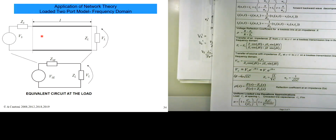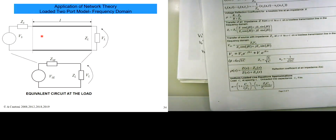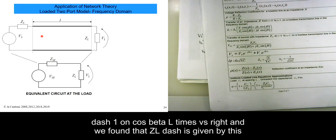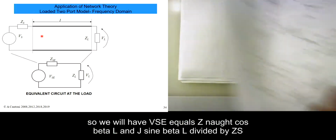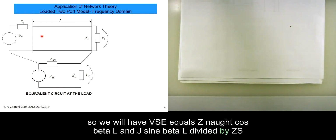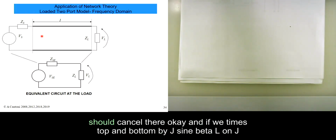We've got VS ZL dash on ZS plus ZL dash equals VSE cos beta L. So VSE equals ZL dash on ZS plus ZL dash, 1 on cos beta L, times VS. And we found that ZL dash is given by this, so we will have VSE equals Z naught cos beta L on J sine beta L divided by ZS plus Z naught cos beta L on J sine beta L, times 1 on cos beta L times VS, so that should cancel there.